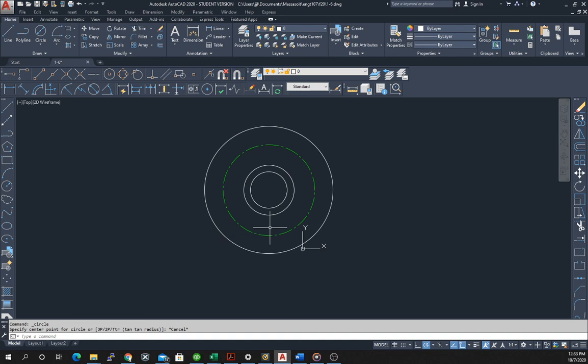Now, before I place it, I'm going to take a step back and remind you of the settings that you need to have down here in order for this to work. Well, we need to have our snap cursor to 2D reference points on, our object snap. We need to show our snapping reference lines.